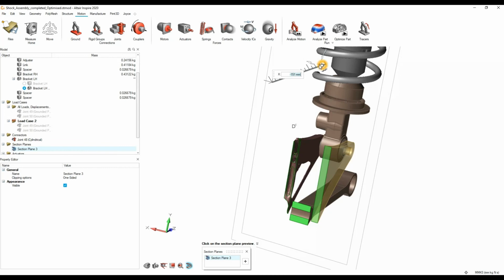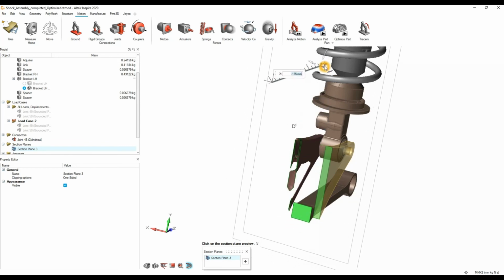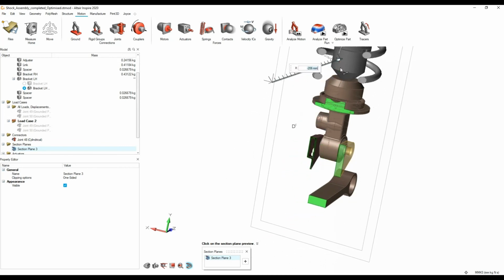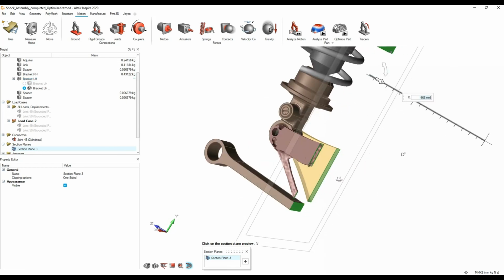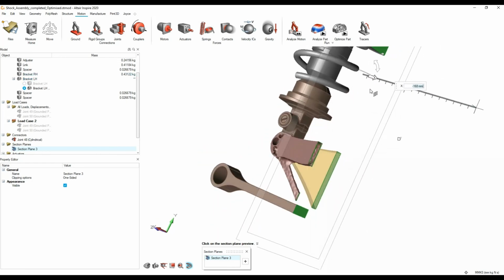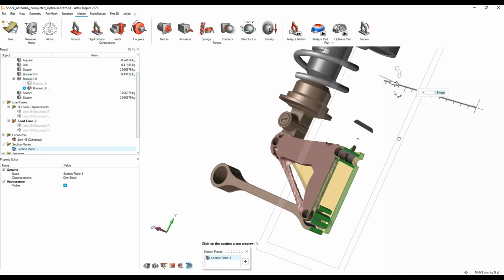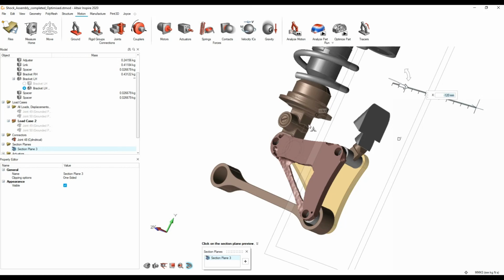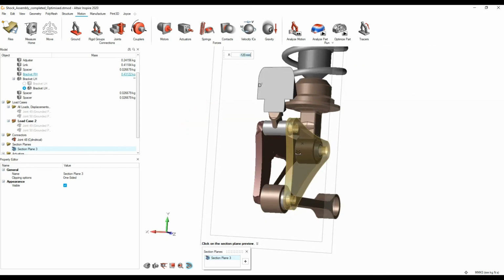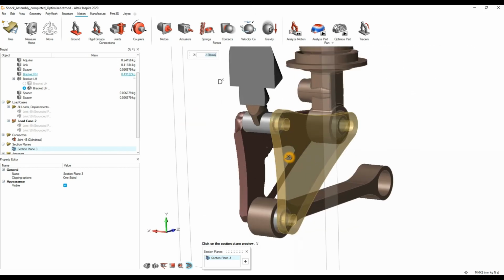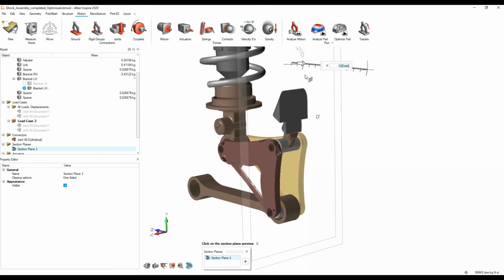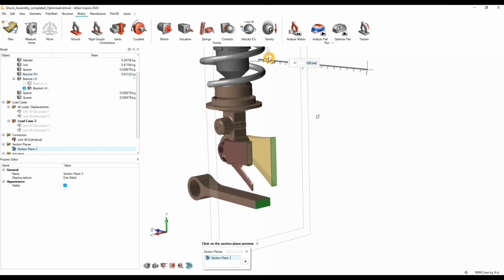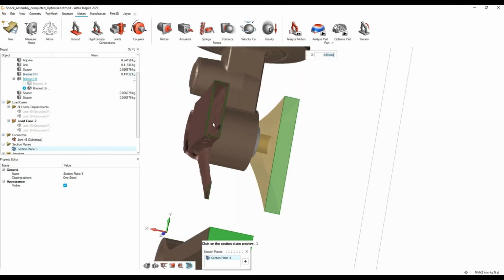So you can see it's quite a hollow shape, and then it's down to you as an engineer to interpret how you want to redesign this part. You can make it with solid beams, it doesn't have to be hollow, it just needs to be lighter than what it previously was, and you can redesign your part. Previously it was a thick solid like this bracket here, and then it tells you to hollow some of the areas out as well.